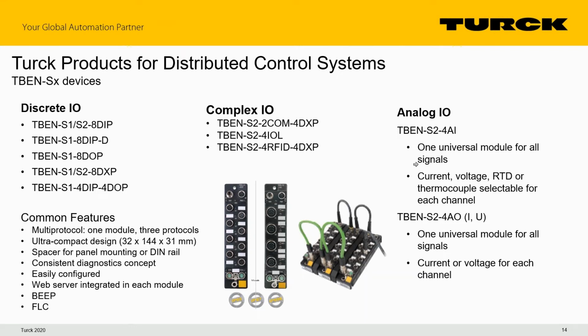As far as our analog inputs, we have a 4 analog input block. This is unique because it has current, voltage, RTD, and thermocouple, all individually selectable by port and all selectable by software. So you buy one module and use it for whatever analog you need.